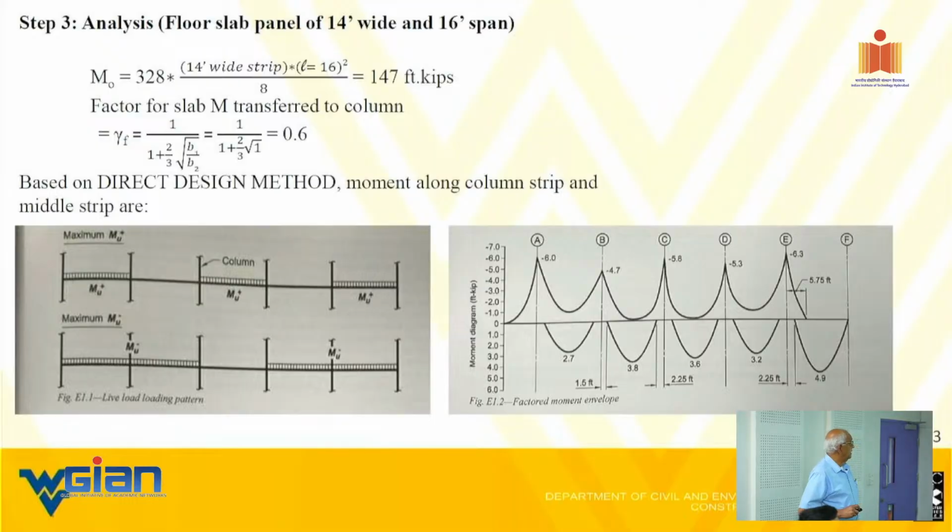Look here, live loading patterns. You as designers, you all know for the alternate moments, you'll get a maximum positive moment. For a contiguous thing, you get a maximum negative moment. That type of a thing is standard, very standard influence line based concept, right? Okay. So they further went ahead and gave you this.